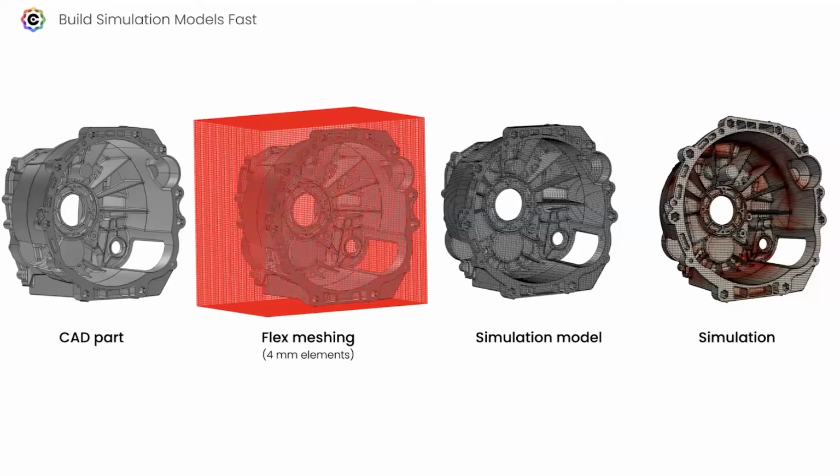So for example, in this case, we take this CAD part here and we immerse it in this mesh that's composed of B splines, degree 2, C1, first order continuous functions. So the first derivative is continuous, and it's degree 2. And this is what we call a quadratic B spline. And we immerse this CAD object into this B spline mesh.